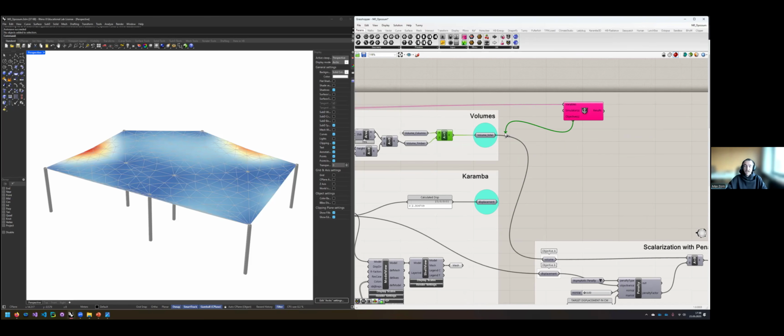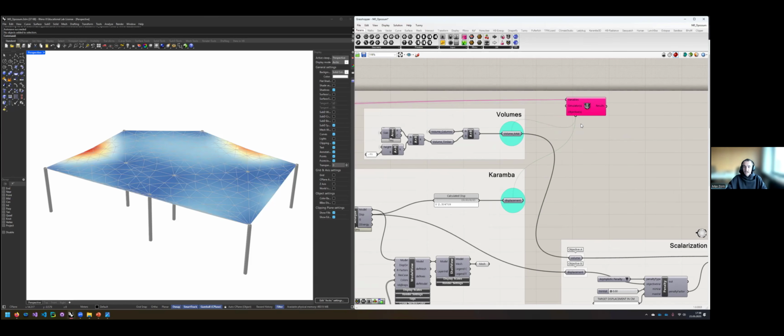So if you see "expected double got NaN" as your error message, then it's most likely because you didn't connect a number container as your objective. Anyhow, I now connected two objectives.